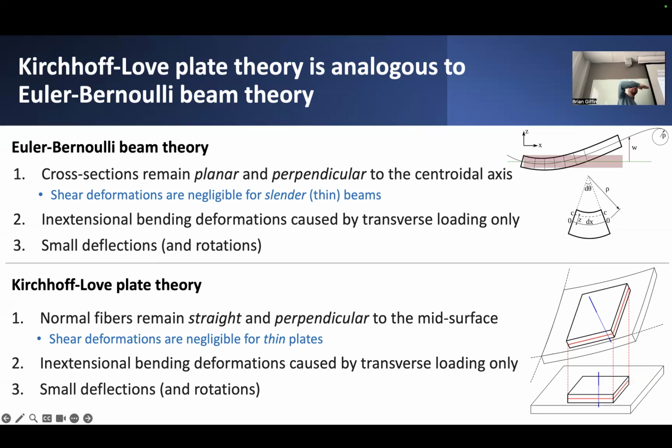It's a particular elevation through the depth of the beam at which it passes through, let's say, the centroid of the cross section of that particular beam. There's an analogous interpretation of a neutral surface in the case of plates. Sometimes it's called the mid-surface, but it basically constitutes the exact midpoint or mid-plane of a particular plate.